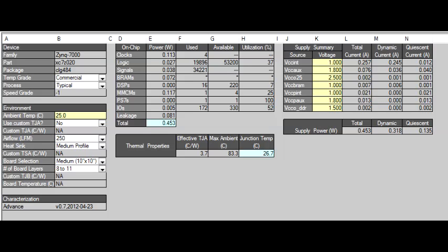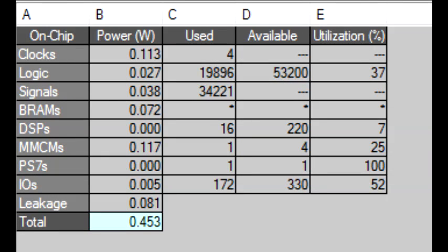So that is the reason I put in the system .bit generated from the Xilinx tools. With XPower, it's also a Xilinx tool, it gives you a summary of all the consumption. This information is only statistical, so it depends, of course, on the system that you implemented, on the design, but it's only statistical. It's not a measurement in real time.